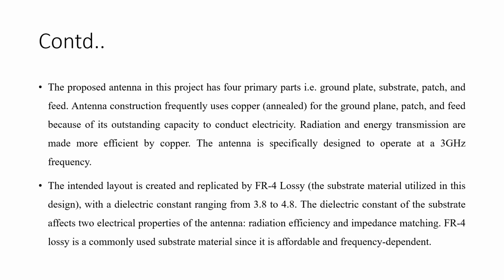The antenna is specifically designed to operate at a 3 GHz frequency. The antenna layout is created and simulated using FR4 lossy with the dielectric constant ranging from 3.8 to 4.8. The dielectric constant of the substrate affects two electrical properties of the antenna: radiation efficiency and impedance matching. FR4 lossy is a commonly used substrate material since it is affordable and frequency dependent.